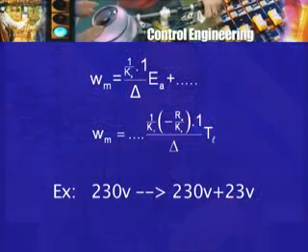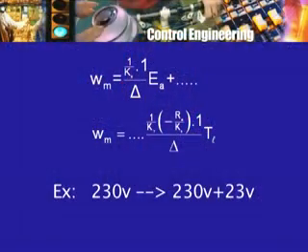So the expression is such, and we cannot help it, because the dependence of the speed on the parameters is not linear. It is not in our hands, it turns out to be non-linear. We can't do anything about it. Whereas the dependence of the speed on the armature voltage and on the load torque does turn out to be linear, and therefore the signal flow graph analysis could be done, because we simply had multiplying coefficients or transmittances, and therefore we finally got coefficients multiplying Ea and TL.